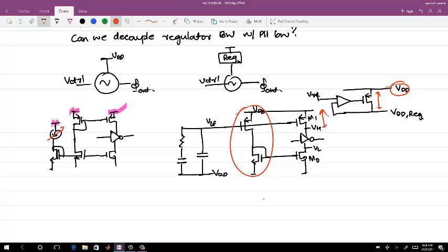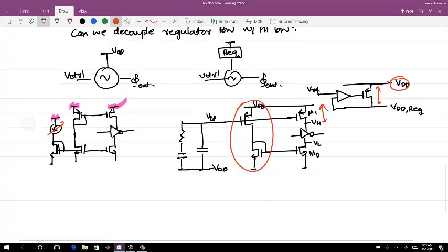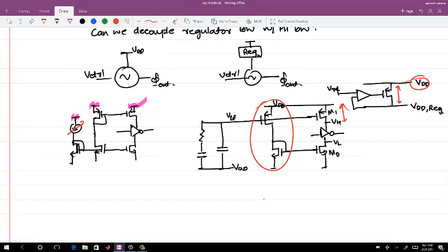For very low frequency of operation. Yeah, then I will come with an argument. Then why are you investing more power? See, if you increase your VDD for the same amount of oscillation amplitude, then you are losing on power. Okay, I mean, there might be places where you do this, but it depends what the final goal is.